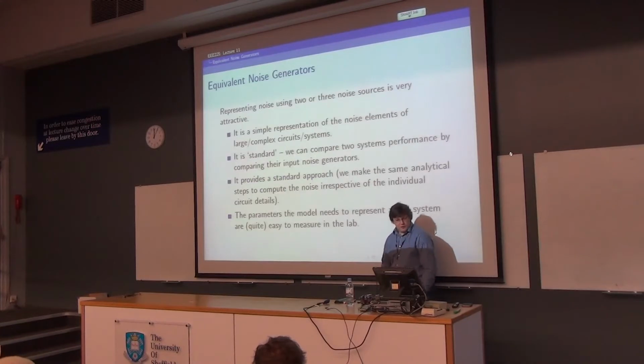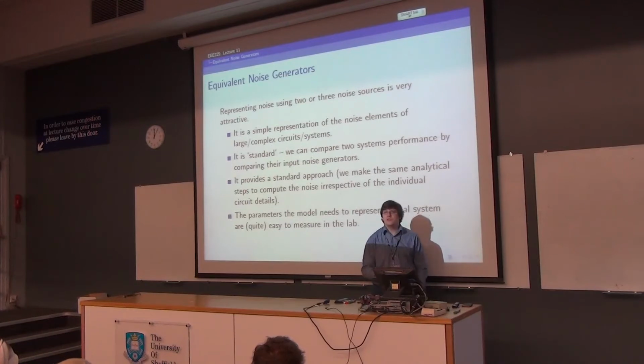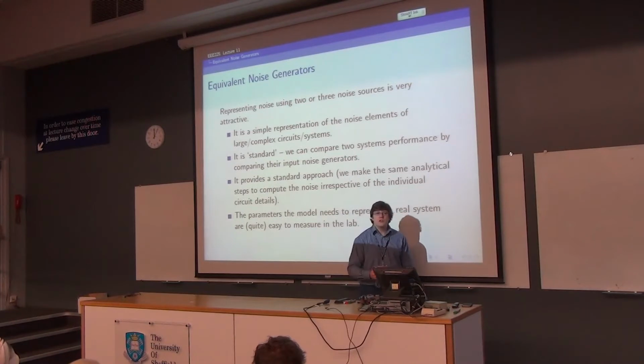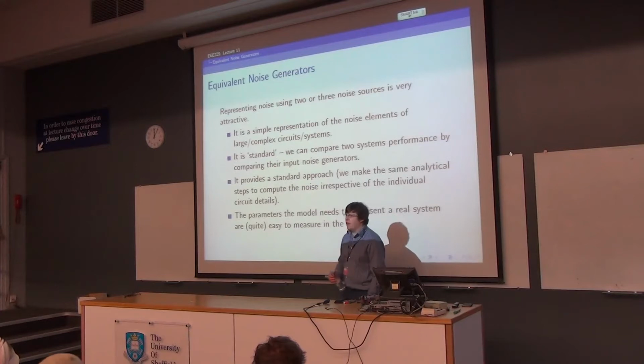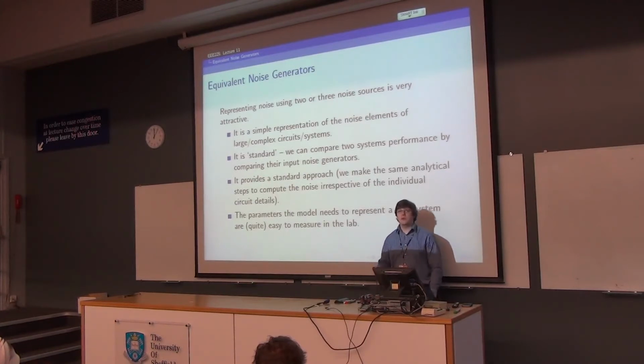to. So, noise generators. We will have in our system a very large number of noise sources. Every time we put a transistor in, we'll get at least one noise source. And every time it will be a shot noise source. Every time you put in a resistor, you'll get a thermal noise source. So if you had 6 transistors in your op-amp and another 6 resistors, say, that puts you up to 12 noise sources, which you have to work out how much effect they have at the output, and then square them all, and then add them all up, and then square root them to give you an answer.